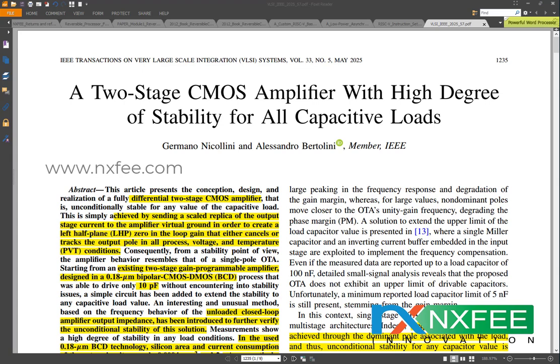The main aim of this work is to study how these challenges behave when the same OTA circuit is implemented in 45 nanometer and 22 nanometer. We compare their intrinsic gain, power consumption and the minimal supply voltage required for stable performance.